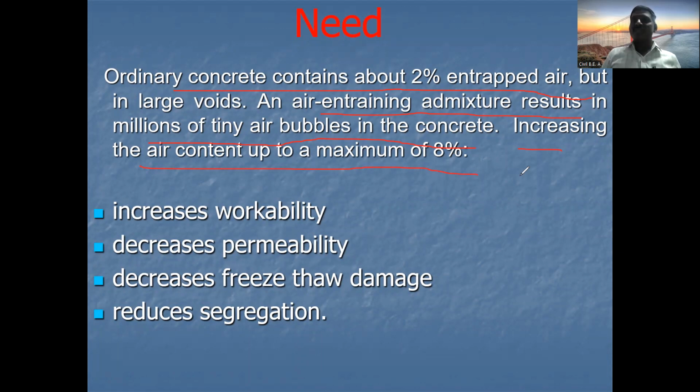So generally 2% of air is available in the concrete. If we go for the mix design, as in the IS code they have given, 2% of air is available in the concrete. If we make the concrete, 2% air will be there. But if we add the air entraining admixture into the concrete, the bubbles increase and the percentage of air increases up to 8%.